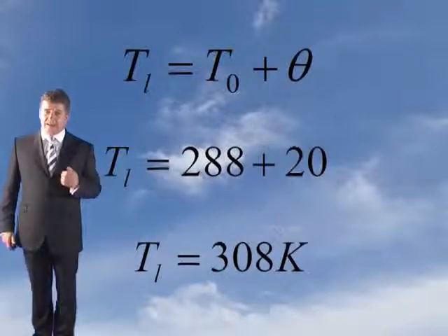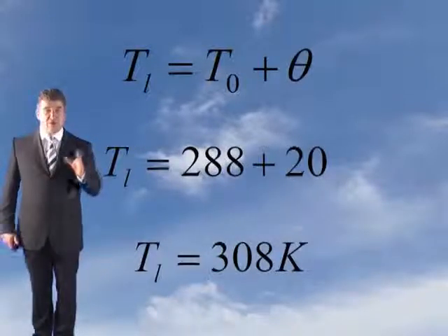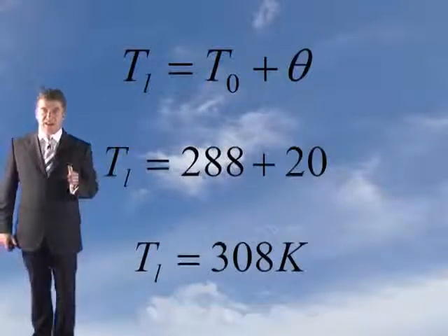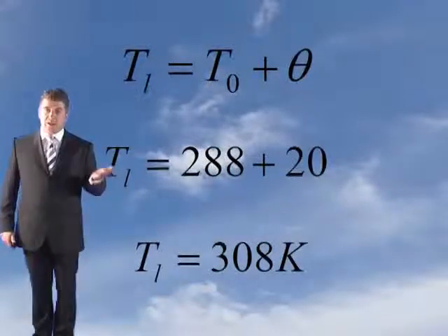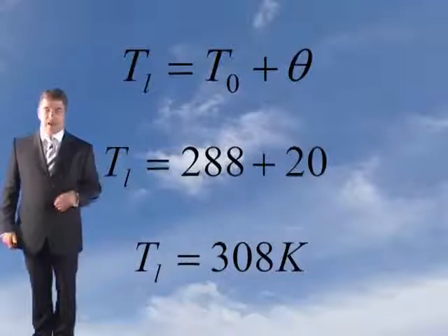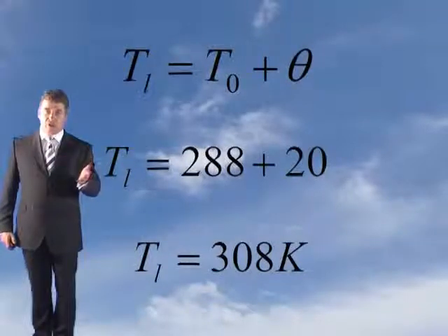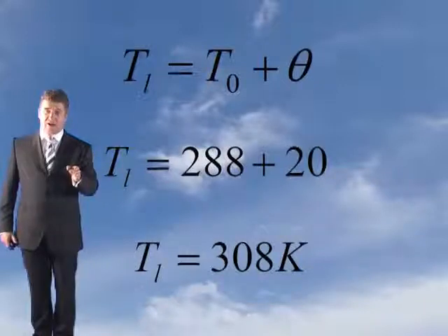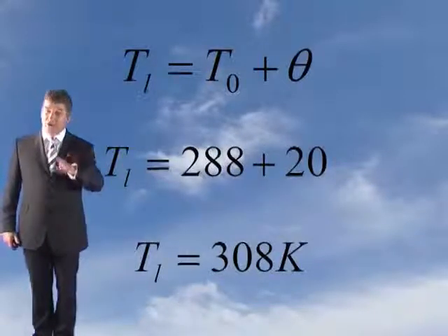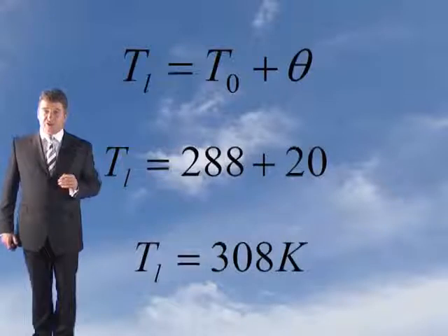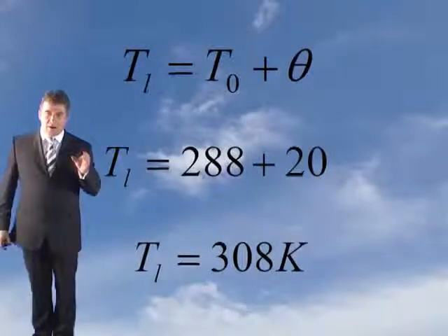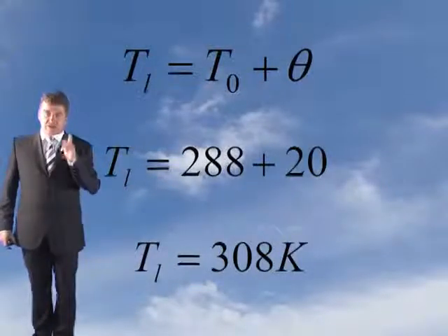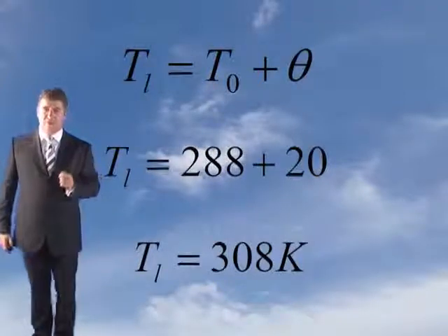Don't forget, it's important to remember at this point, if the smoke was over 200 degrees C, it's untenable for life safety. Well, in this case, it's well below that, and like I say, it's still got the buoyancy at a 20 degree increased theta value. Anything less than 20 degrees, you can't use natural. And in fact, really, you shouldn't be using mechanical ventilation, unless you've got other factors. 20 is the critical factor. You've just met the 20 degrees, so it does do that. So we know how much smoke we've got and how hot it is.